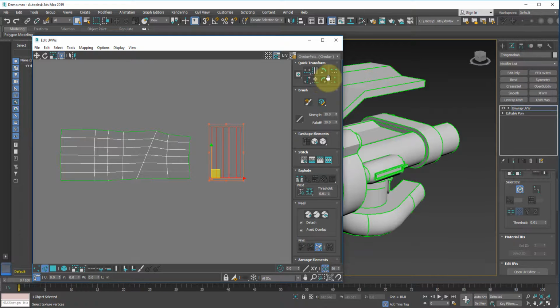Then the last two sets of tools that we see over here are your vertically and horizontally spacing tools. The way this works is, let's just say I want to grab a bunch of vertices here. I can grab this edge here, hold down Control, and select the vertex mode to convert my edge selection into a vert selection. Keep in mind, this method will convert any subcomponent to another.